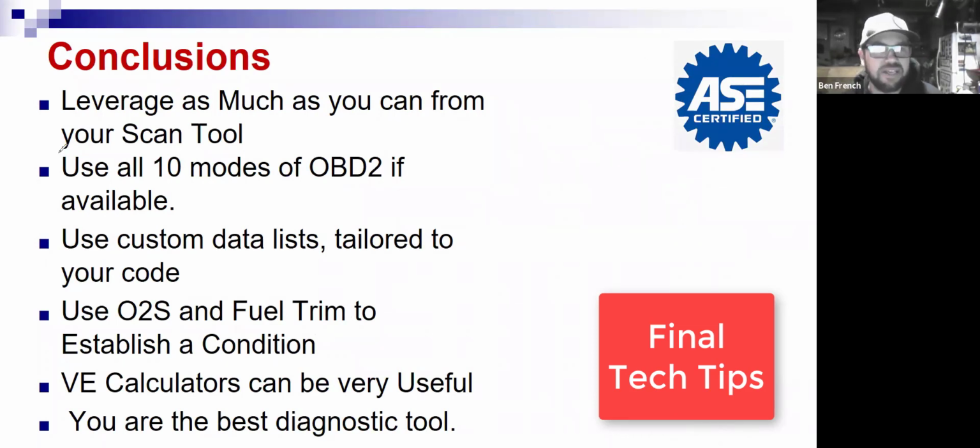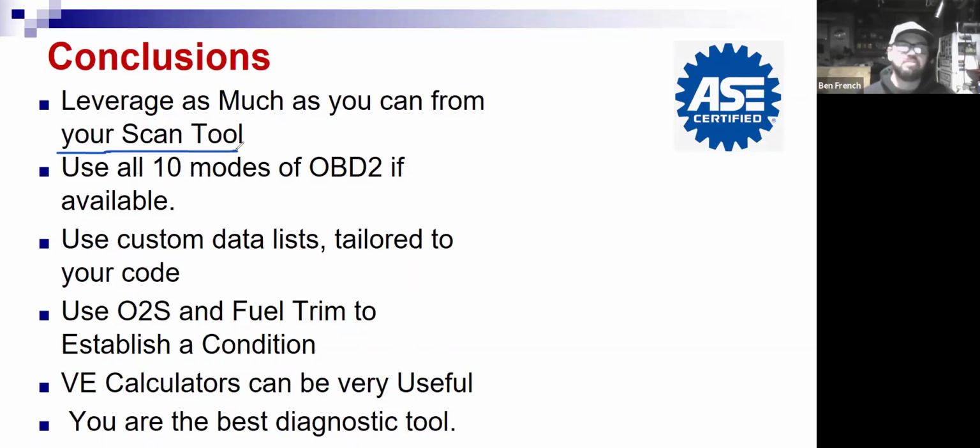And that's been the theme of our class: whatever scan tool you have, whether it's a Snap-on Solus Ultra, whether you bought some real slick new Autel, those are nice tools that are out on the market these days, or a factory tool, or your little cell phone ELM interface. Try to get the maximum amount of usage out of that. Read the owner's manual, play around with it, scan cars that don't have anything wrong with them just to learn that tool and learn those cars.